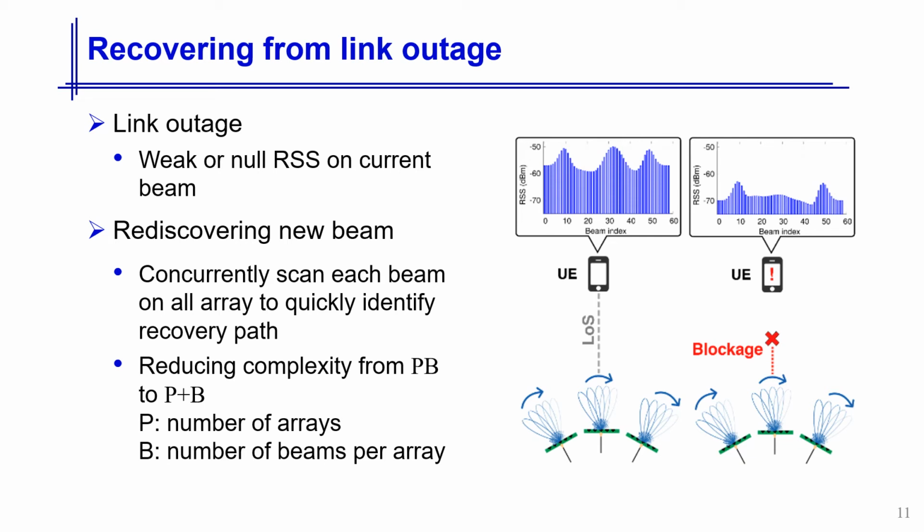It is well known that millimeter wave links are prone to blockage. To handle the blockage, we propose a simple concurrent beam swapping scheme taking advantage of APA structure. Upon blockage, the AP loads all arrays with the same codebook to find the best beam index. If any strong line of sight or non-line of sight path exists, then at least one beam will lead to a strong AOD peak.